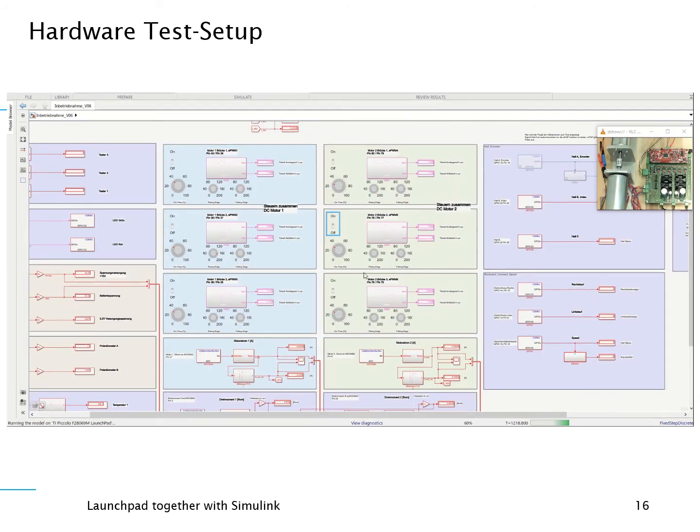Sorry, I forgot to show you the half bridges in action. Like I said, we have 6 half bridges, as I'd like to use the hardware to drive a BLDC motor. Today we use just 4 half bridges, together making 2 full bridges, 1 full bridge for every motor. So we have here the upper right MOSFETs for motor 1, and the upper left MOSFETs for motor 2.